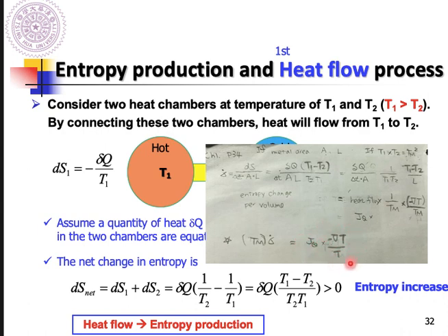This extra term we call the driving force that drives the heat flow in the heat flow process. So we have successfully demonstrated that in the heat flow process, we can also derive this universal equation, which is the absolute temperature times the entropy production rate equals flux times the driving force. But please pay attention here.